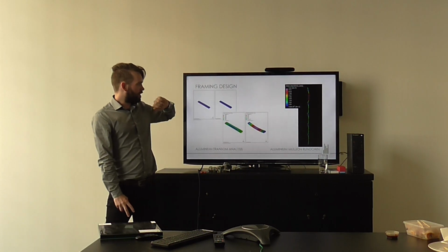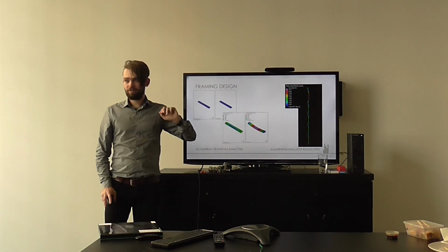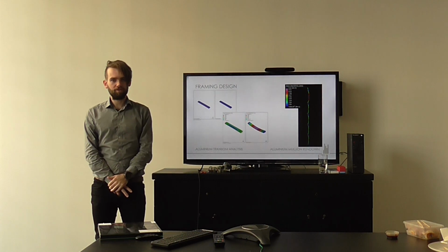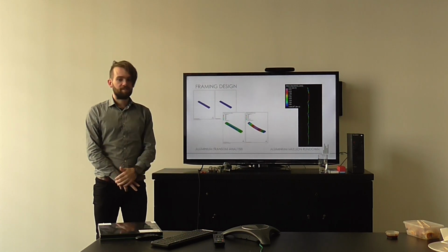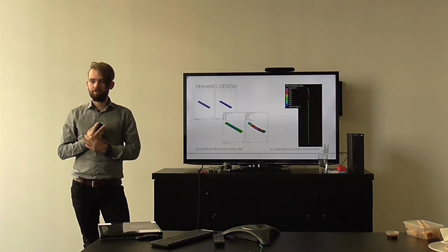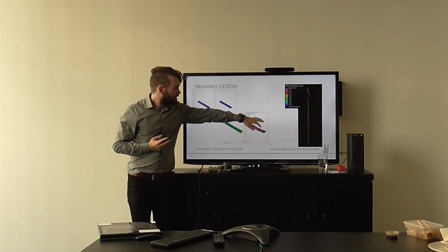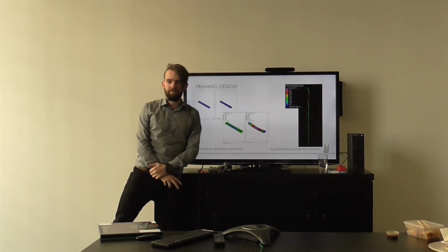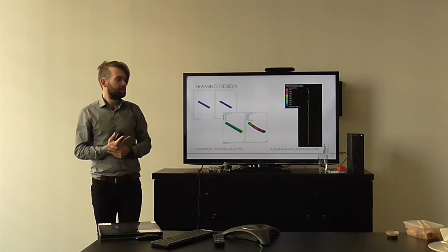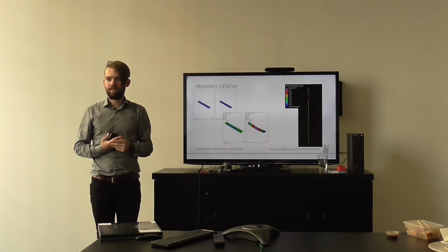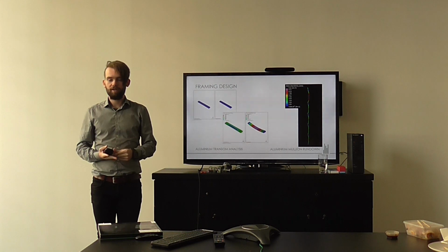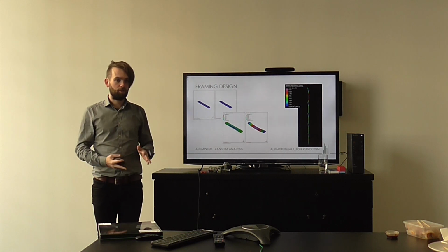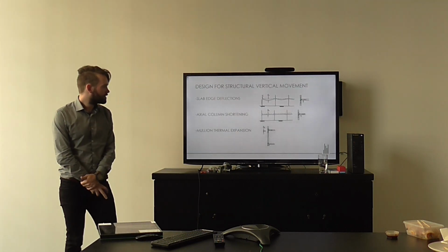The diagram on your right there is of what we call a mullion rundown, which is typically looked at in a curtain wall, where you essentially model a portion of the split mullion of the curtain wall with stack joints and brackets to represent the behaviour, and we can then check that our displacements are right and stresses are right. It also assists us in getting the loads to check our brackets.